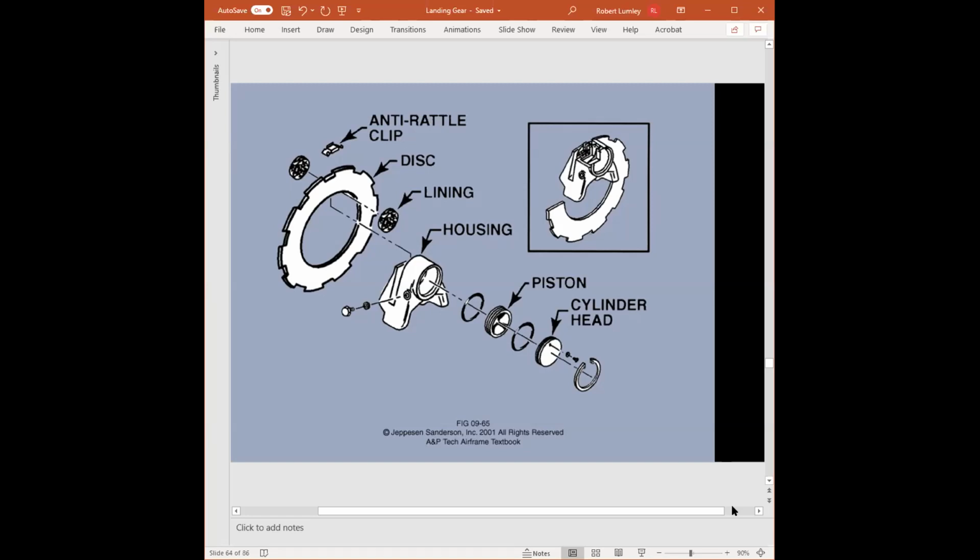If that pad comes in direct contact with the piston, it can create a thermal conductor so that the brake fluid gets hot and boils, which is not good, because if it boils it can actually coke up. It solidifies, which can then block passages and stuff like that. So always follow the manufacturer's recommendations.